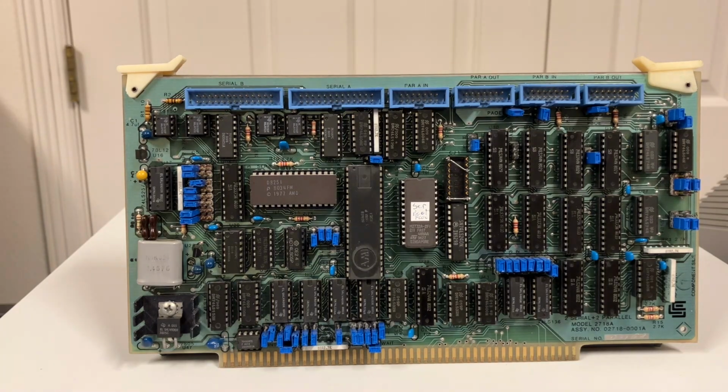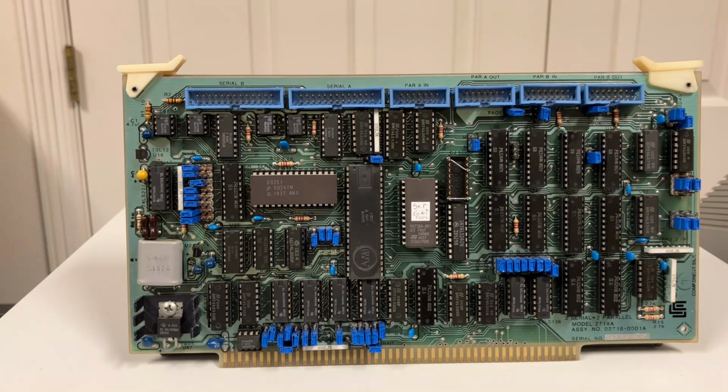Now, one kind of neat thing about this EEPROM is that it only takes up as much address space as you have programmed. And it does that by, whenever the data is an FF, whenever it's returning all ones, which would be like if nothing was there, or an empty spot in an EEPROM, it does not enable the bus drivers at all. But it still looks like an FF to the CPU because there are pull-ups on the data pins on the CPU board in an Altair and an MSI and several other early CPU boards. Or at least if you have termination resistors, or active termination even on the bus, then an open, nobody driving the circuit, will also look like ones.